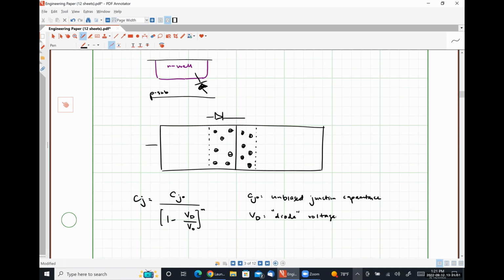voltage applied, where forward bias conditions would have a positive polarity, because we should expect that a forward bias PN junction has more capacitance than a reverse bias PN junction. So recall just really quickly, when we move the plates further apart, the distance between the plates gets greater, which means the overall capacitance gets smaller here.